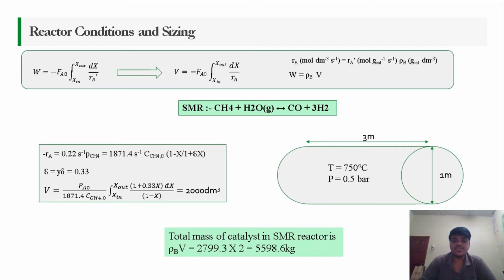This is because the SMR is an endothermic reaction, and conducting it at a high temperature will eliminate the reversibility of it. And SMR is also known to have a side reaction, which is the Boudouard reaction, which is exothermic. So having a high temperature will minimize it and eliminate it as well.